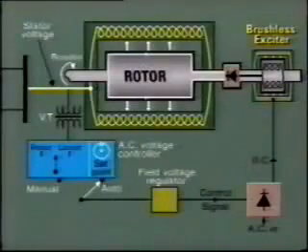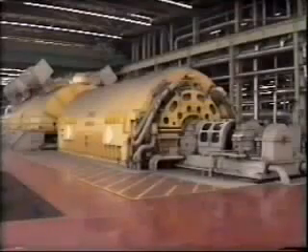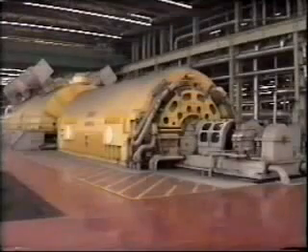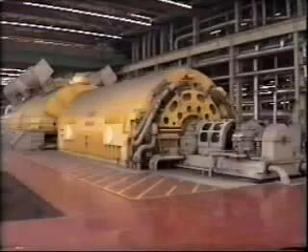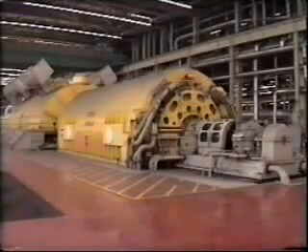This is basically what's done in the brushless exciter, which provides the excitation voltage or rotor voltage for some AC generators. This will be discussed in segment E of this tape. However, this is not a practical arrangement for large AC generators, as huge slip rings would be required to take the large AC generator output current from the rotor.